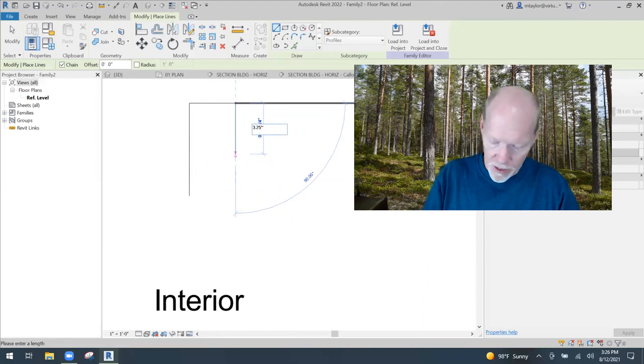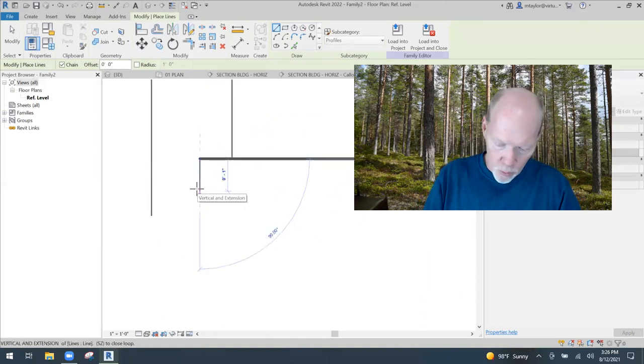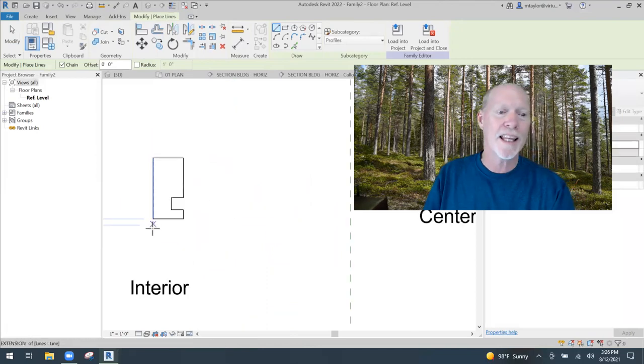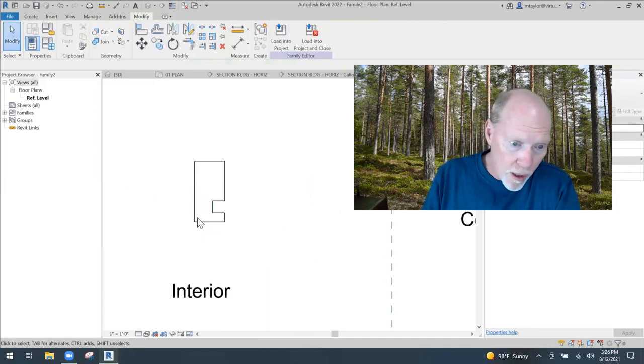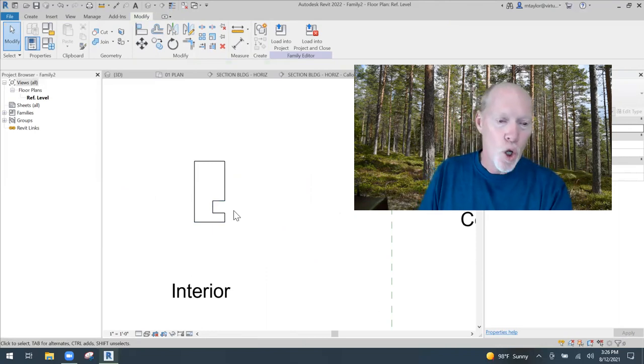3.25 inches. And then we've got a little pocket here. Let's say it's a 1 inch pocket, 1 inch wide, and comes back. And then there's our 3/4. So basically, this is the mullion that we want. This is the shape we want. Now, your contour shape could be anything, but I'm just saying, this is the 3/4 inch back. The glass is going to go right here.